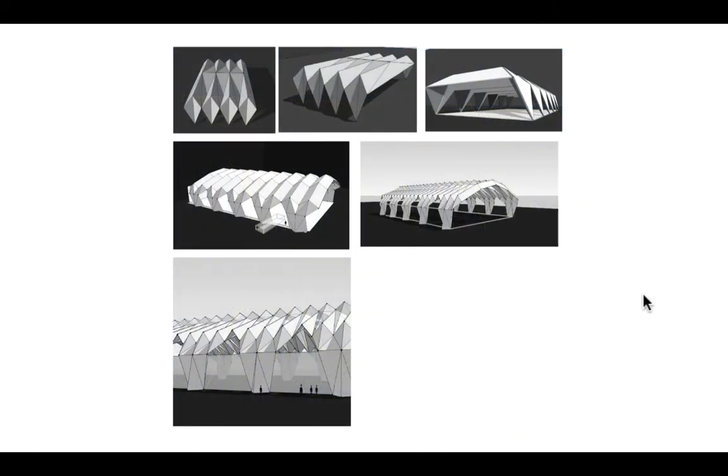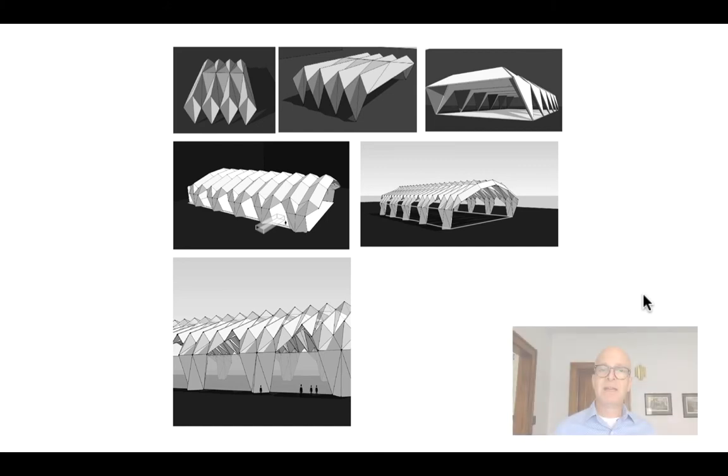We can tune the folded plate too so that we can bring equipment or people in not just from the ends, like in the kind of basilica plan, but also from the sides. And here you see sort of clever solutions about taking the folds not only across the span, but also using the folds to create what are basically columns. And the geometry of this is such that we get a very good portal frame shape out of it, right? Deep at the corners, shallow at the bottom and at the top. So again, kind of like a three-hinged arch.